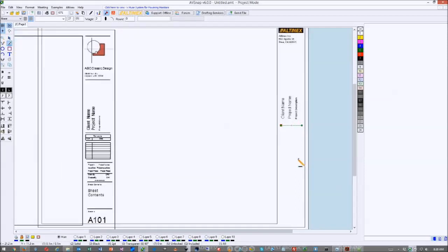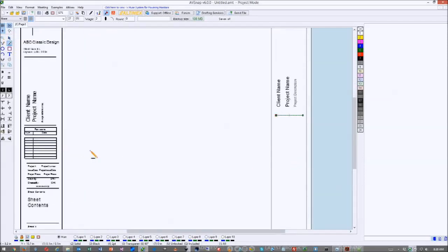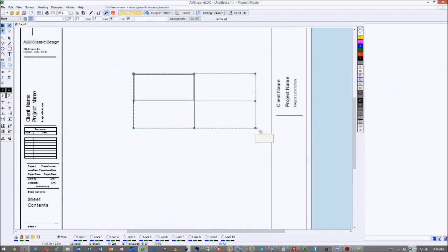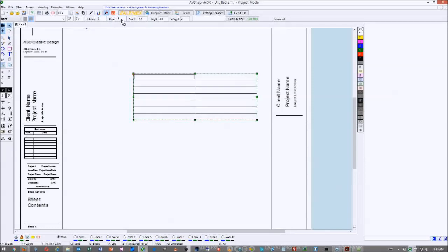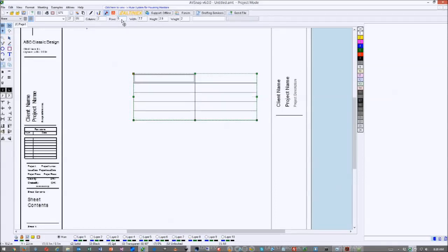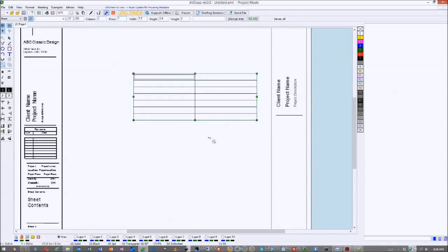Now, you can do this section right here a couple of ways. One of them, you can create what we have, a table object. So if I use a table object, I can create a table right from there. And you can see right here on the top, you have number of columns. You can adjust just by scrolling over. So in this case, I need 2 columns. And number of rows that you can adjust. So in this case, I may create 6, 7 rows, which is going to be my text.